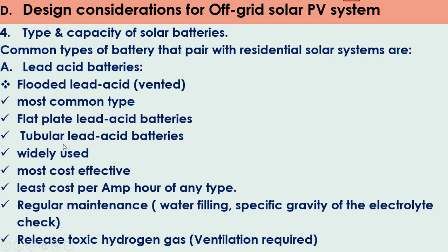This kind of batteries, lead acid batteries, requires regular maintenance, which means water filling and checking the specific gravity of the electrolyte.